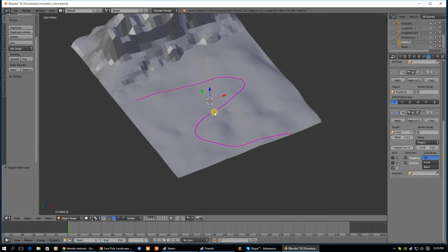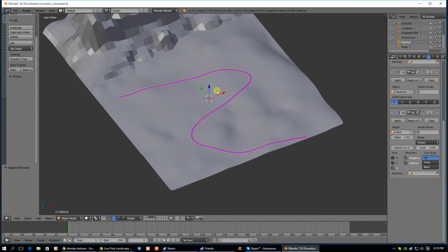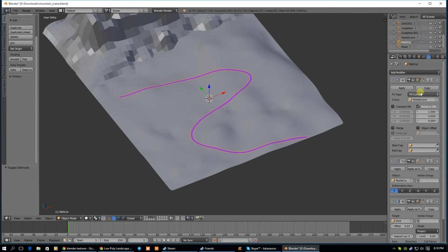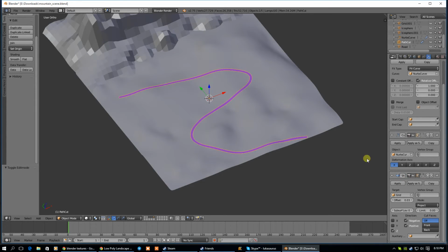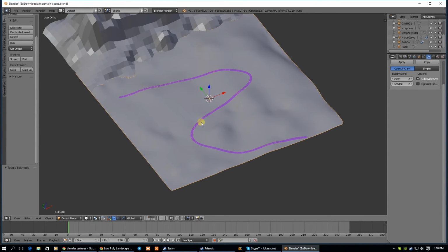Okay, so the main thing to take away from that was you draw your path, you draw your road, you set up the road with an array modifier and a curve modifier, and that'll give that all the way out there. Then you shrink wrap the NURBS thing to the curve, but everything should have the same active center, and if it doesn't, that's when you get the odd thing.